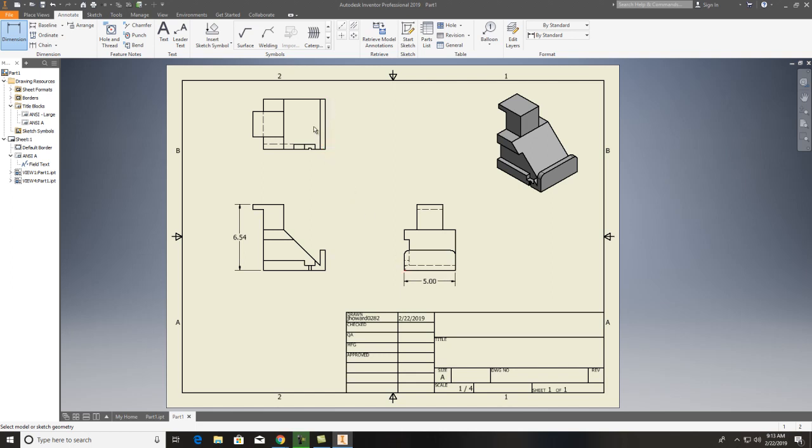And you know, you've got your depth here, so there's no reason really to put your depth on this. I mean, you could, it's either or, because you just don't want to over dimension something. And we can go up here and put, you know, things like that. So just think about that when you're looking at these things. There's no sense of putting a dimension here and then coming up here and putting the same dimension in because you've already got it one spot. Do you see what I'm saying? Or it'd be like transferring this height dimension over to the right side view because you've already got it. All right, you just don't want to over dimension and crowd and clutter things.